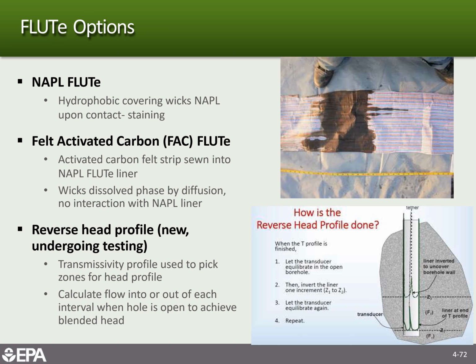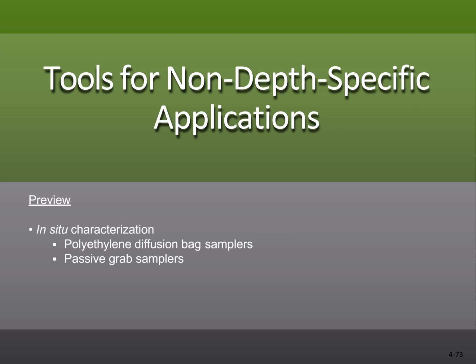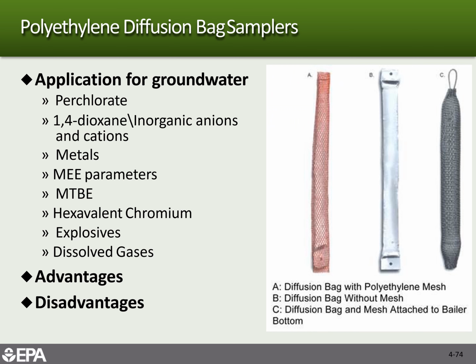One of the other uses of this is if you have a borehole that you need to seal, but you haven't had a chance to design the well to go in there, then you can use this to go into the hole and seal off the formation so you don't get cross-contamination. So for some non-depth-specific activities, you can use passive diffusion bags.